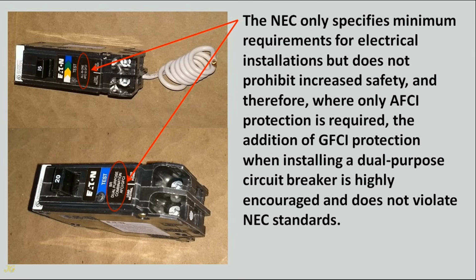The NEC only specifies minimum requirements for electrical installations but does not prohibit increased safety, and therefore, where only AFCI protection is required, the addition of GFCI protection when installing a dual-purpose circuit breaker is highly encouraged and does not violate NEC standards.